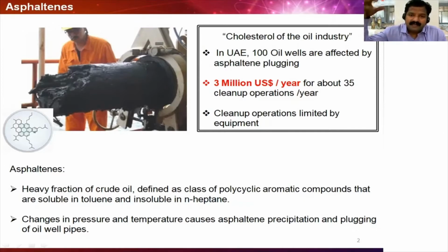Then one day, we try to drill this oil out. From its stable conditions of temperature and pressure over millions of years, the oil suddenly encounters abrupt changes of pressure and temperature, and these conditions trigger the stabilized asphaltic molecules to aggregate with each other and form asphaltic aggregates and final depositions. That happens very quickly, plugging the whole oil well.